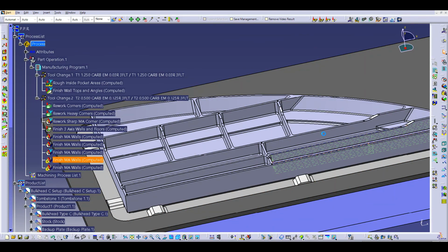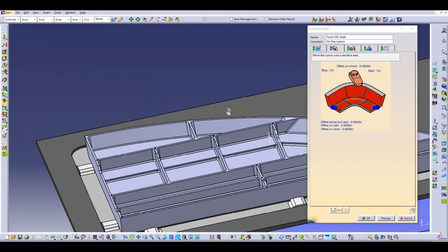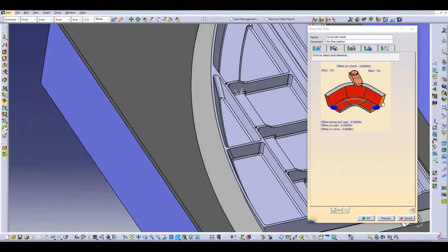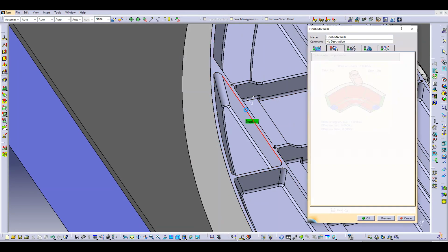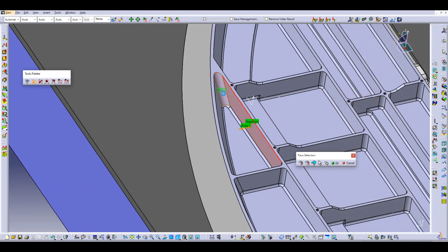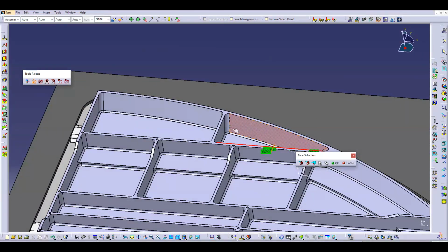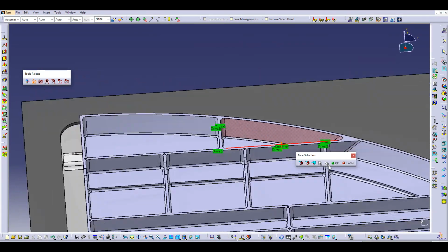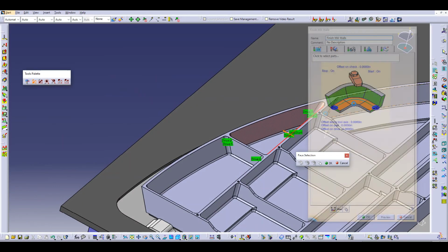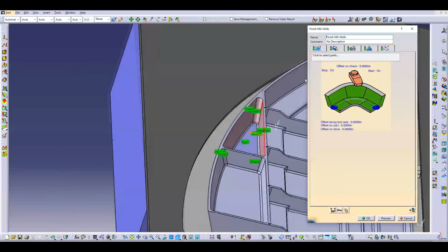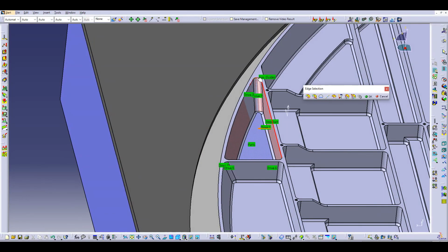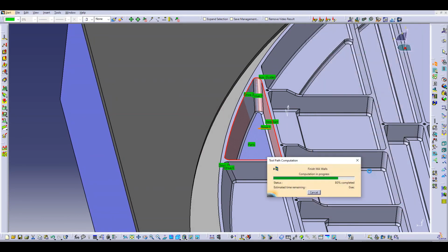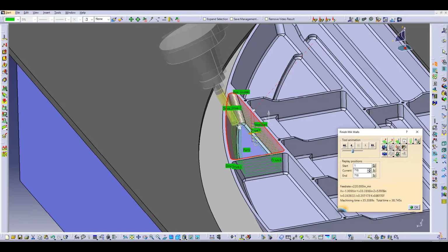Now the next one is this steeper pocket wall. It's the one we had the special rework for. But we'll machine it the same way. I'm going to show you one extra little thing I'm going to do when I machine it though. And we'll use our navigation. And you can actually, the next one, you could click that and you can navigate it too. But this time, just because of the steepness on this, I'm going to give this an auxiliary guide curve. So I'm going to select this top. And what that means is the cutter cannot violate that. Okay, so we'll watch this run around.